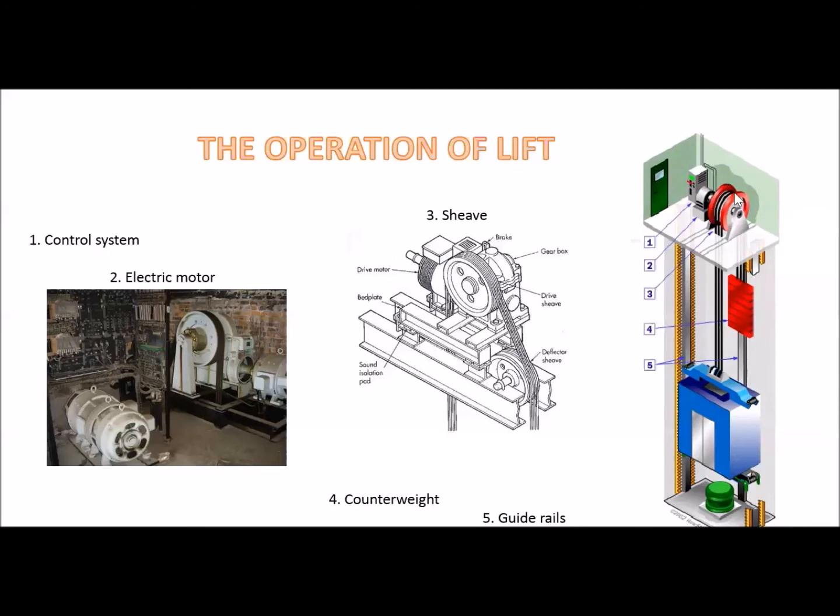The problem that we can face in the lift is if the motor loses a phase, it causes the motor to lose some of its power and creates an imbalance, which causes abnormal noises and vibrations. Besides that, the motor will pull more electrical current from the remaining phases and cause high temperatures when starting the motor. So it means that when the motor wants to start to operate, it will reach a high temperature. But you don't have to worry when this problem happens.